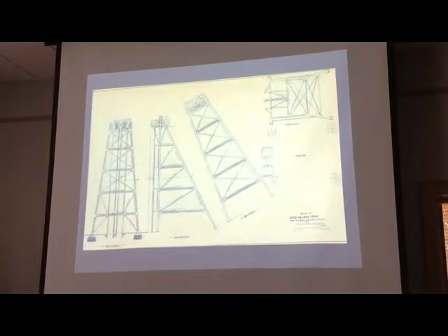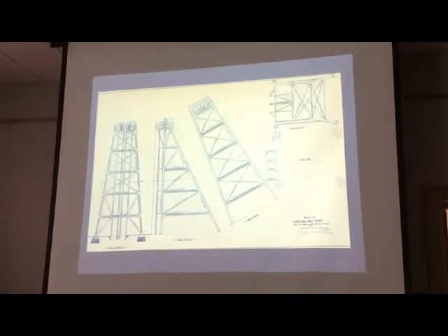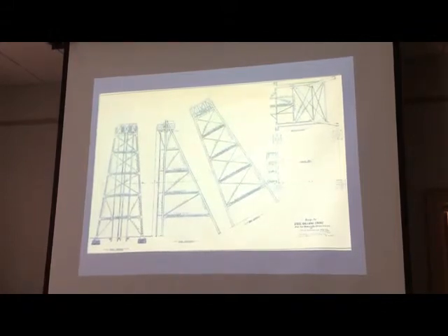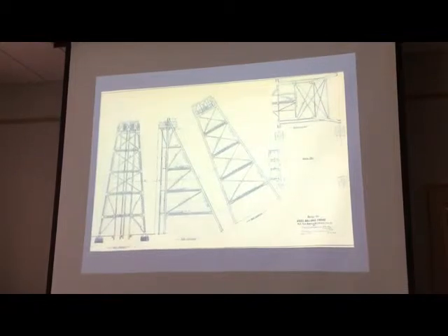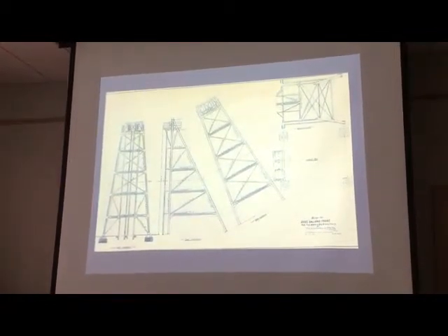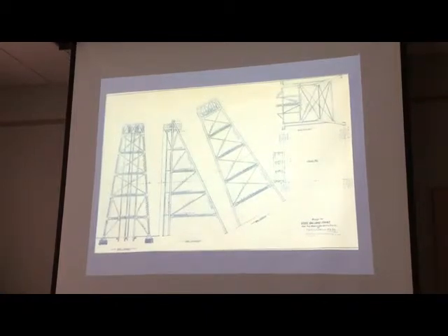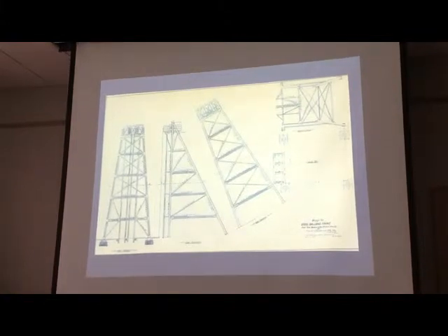And I found a design for the Basin and Bay State. Now this was the design in 1897. This was an extremely heavy 60-foot tall steel head frame that was supposed to go in the Basin. It was supposed to withstand the breaking strain of 1.25 inch hoisting rope along the plane of the back brace. Now, the only hoist in the world that could have done that was sitting in Butte at the time. But this was never built.